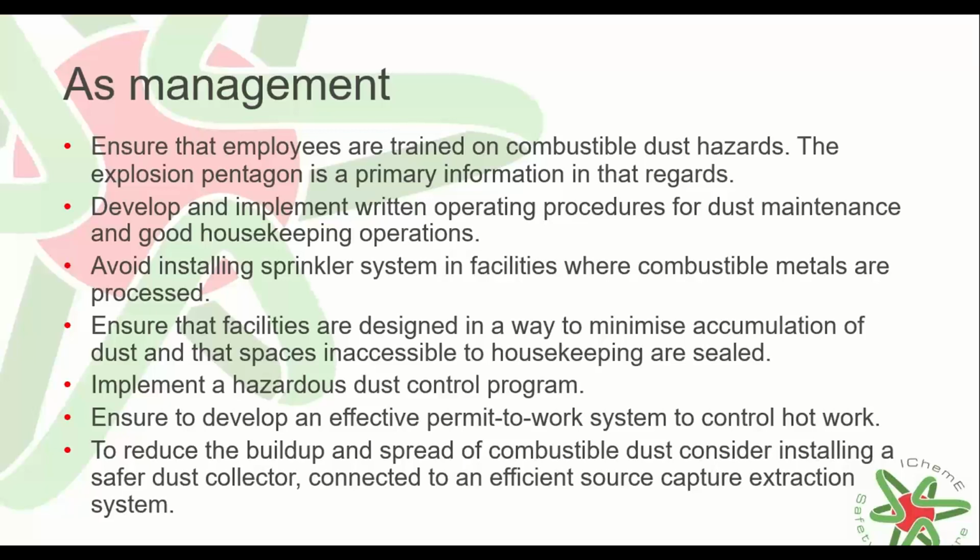examples. What can I do as a manager in order to avoid such cases where dust explosions occur in the facility? Please feel free to add any more if you have more. So knowledge about how dust explosion can occur is key in operation, so ensure that employees are regularly trained on combustible dust hazards to keep their knowledge up to date.